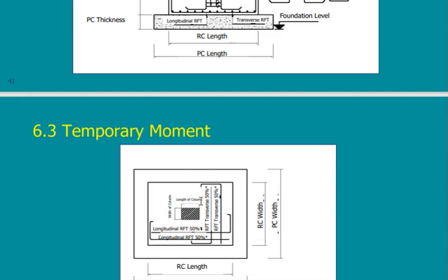Why do we use this or we use a U-shape? When the footing is small and the amount of reinforcement is small, then I use the U-shape. But if I have, like this case, moment in both directions, I have a lot of steel. You remember in beams, we used to have something called curtailment of steel. Do you remember what is curtailment of steel? It's something to reduce the amount of steel. If I have, say, a beam, in the middle of the beam I have very high bending moment, so I need 10 rebars.